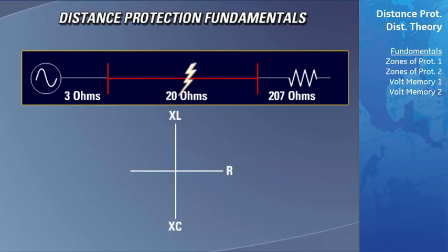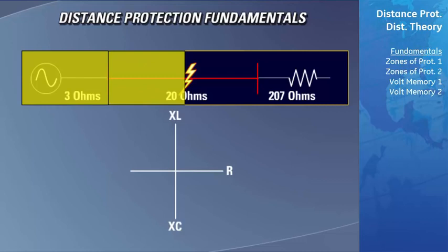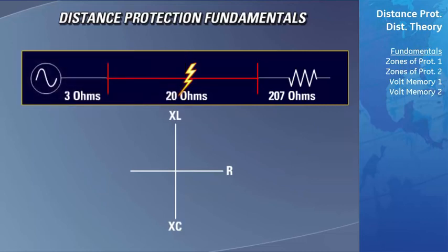If a fault to the ground were to now occur at the midpoint on the transmission line, all of the impedances after the point of fault would no longer be part of the power system. The impedance of the system would now only be the impedance of the source plus the impedance of the transmission line before the fault. The power system impedance is now no longer mostly resistive because the only impedance is now the mostly inductive transmission line.